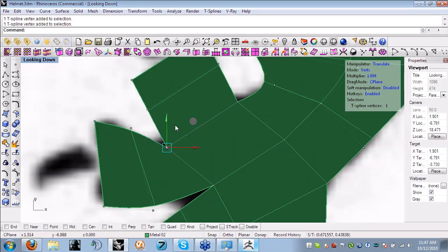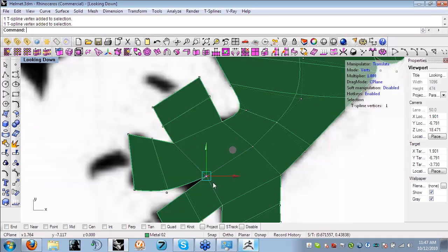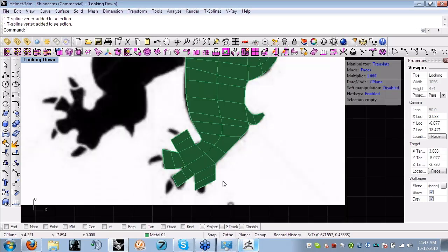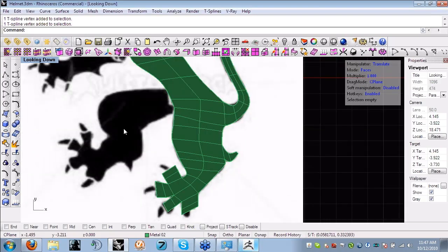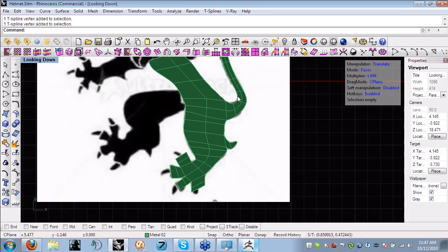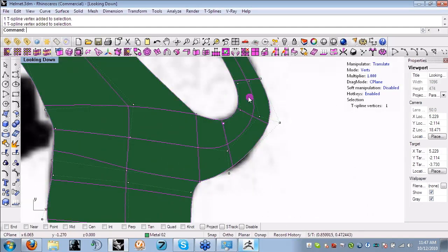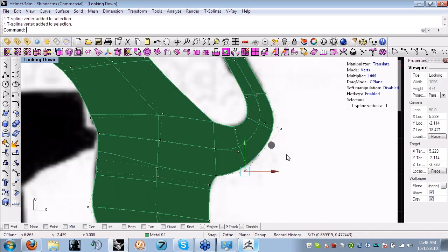I'm a firm believer that all signet style models should always be machined and never RP'd. So I don't worry about it with this particular model. If it is a problem, though, the nice thing is that T-splines are always solids. So unless you turn the faces inside out or something, it's always going to be a nice, perfect solid that will have no trouble doing Boolean union or subtraction operations on.